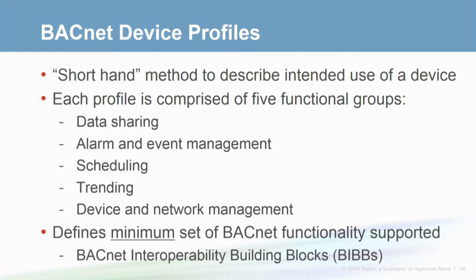The thing to remember about device profiles is that they define a minimum set of functionality using BACnet interoperability blocks, or BIBs. However, most vendors will include additional BIBs to make their devices more feature-rich and better able to meet the customer's needs. When you are comparing 2 devices that support the same device profile, you will need to look deeper to determine if the 2 are actually equivalent by comparing the BIBs that each device supports.